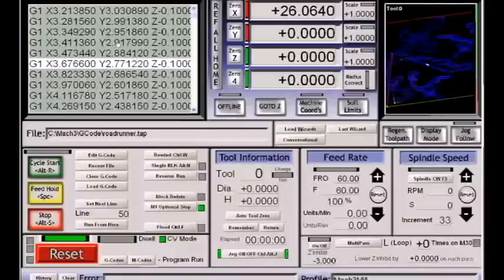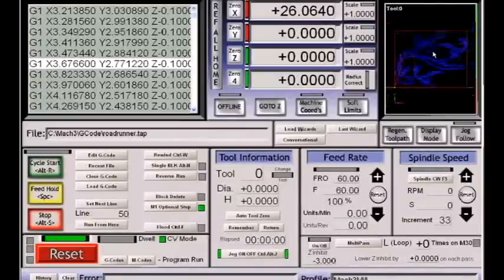Clicking once again will take you out of focus for that window. The Toolpath window itself, double-clicking will reset it to a plane and reset it to a size. The red box going around our toolpath is simply the extrema of the file. The program is telling you this is the highest Y value you have, the lowest Y value, the minimum X, and the maximum X values.